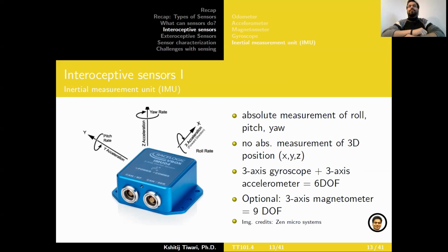So most of your measurements are just going to be estimates, because you're going to be doing integration or double integration to get an understanding of your position or orientation. There would be drift. For example, a magnetometer is affected by the magnetic field of other objects around you. Your microwave oven is a very strong magnet. Your mobile phone has a magnet. A lot of these electronic devices have magnetic components on them, so there would be interference amongst them, and a lot of drift in such cases.